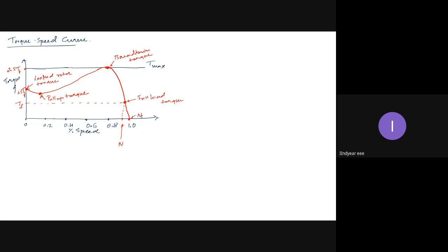there will be an automatic motor control mechanism which is decided by the torque-slip value of the motor. If the speed of the motor falls below a certain level, then before the pull-up torque is reached, the motor stops. How does the motor stop? They will disconnect the stator from the supply. The switch will be opened. The MCB operates or the relay operates and the motor supply is isolated or disconnected.